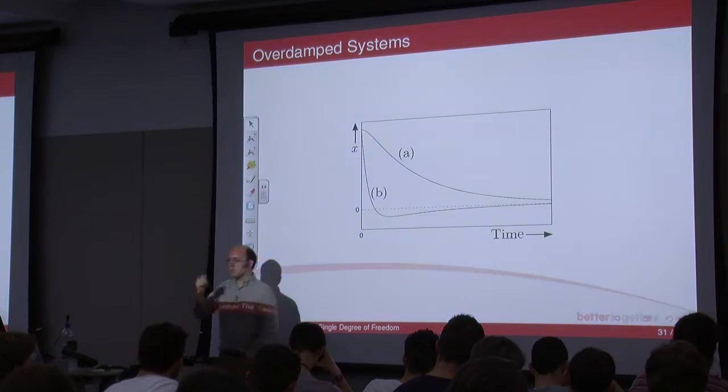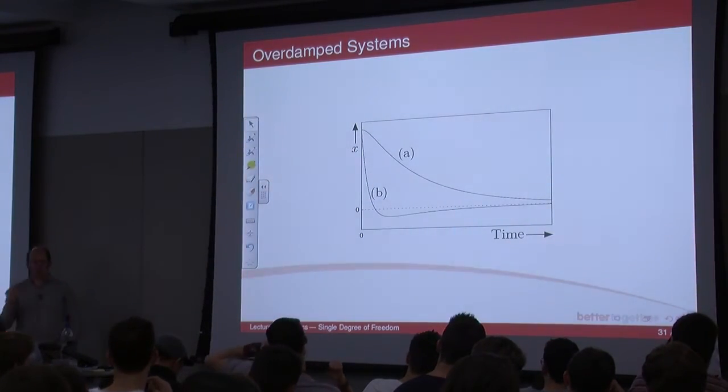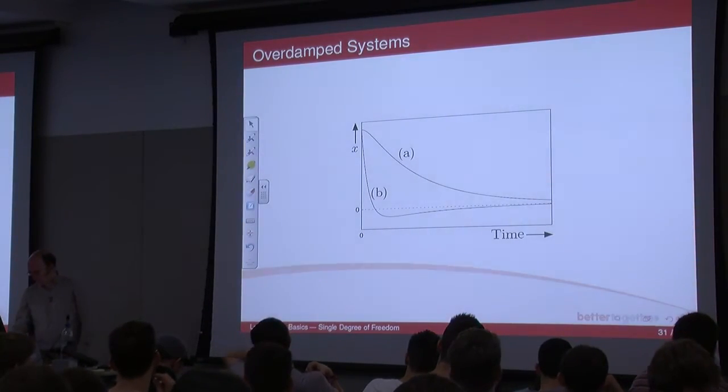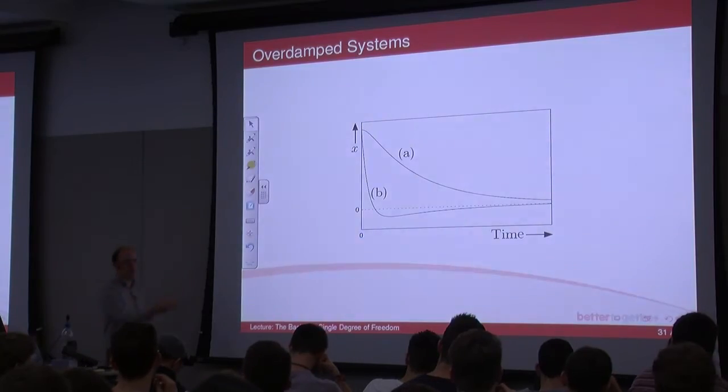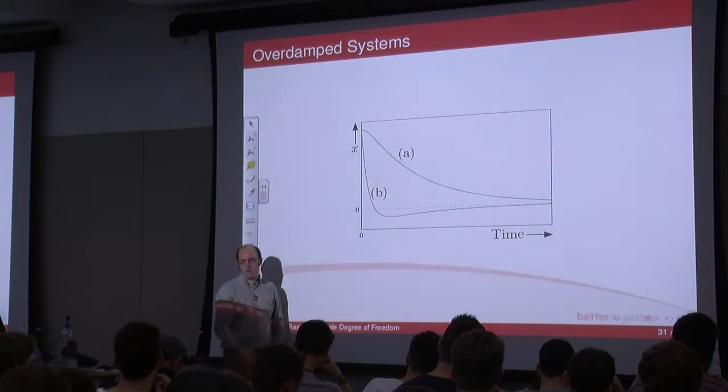An overdamped system will never ever oscillate. Sometimes you want that, often you don't. You want a little bit of oscillation, not much, but a little bit. And basically, it takes a very long time for it to settle. Depending on how much damping you've got, it'll take forever.